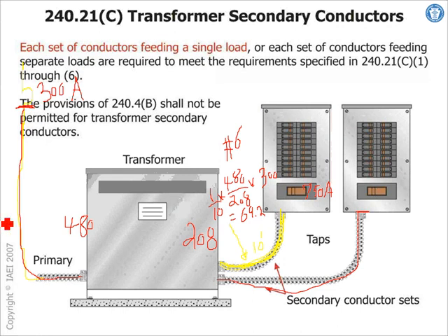Here's the rule for this. The conductor here cannot be less than one-third of the 300. What's one-third of 300? 100. So when you size this conductor, what did we say 100 would be, number 3? Can anybody tell me why the heck the overcurrent protection device would be 300 and the conductor 3? Inrush on the transformer. Right? The inrush on your transformer could trip this overcurrent protection device. Typically, if it's a circuit breaker, we can go to 2.5. So that's the minimum, 3.